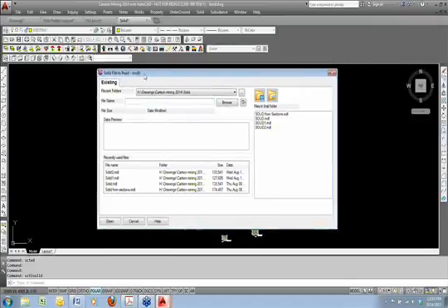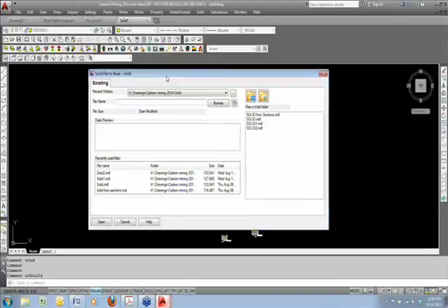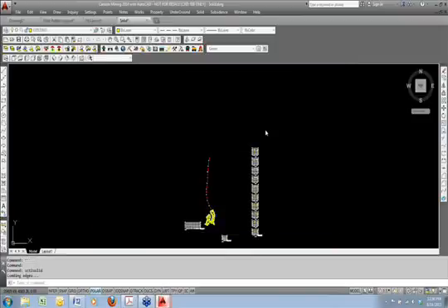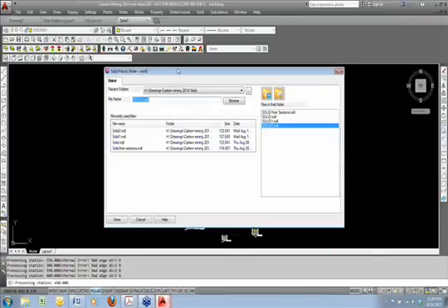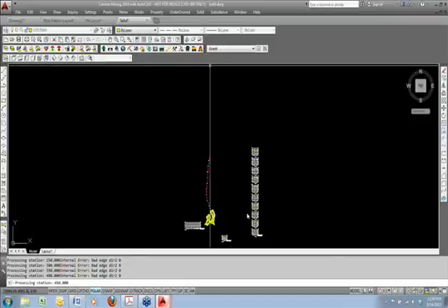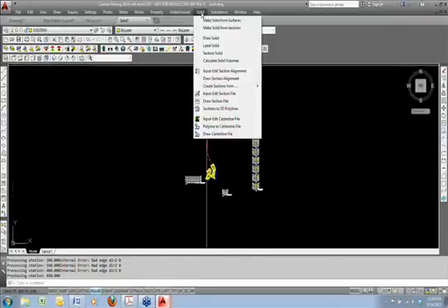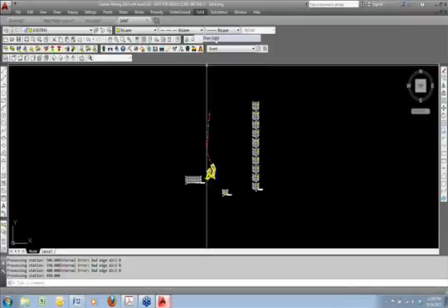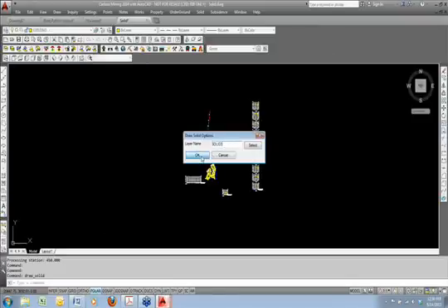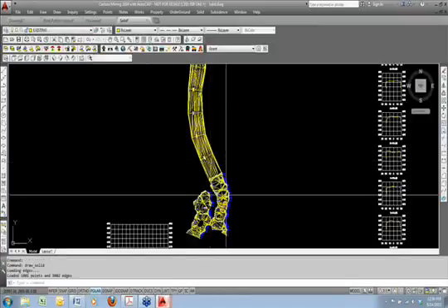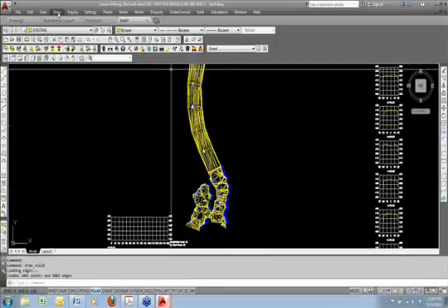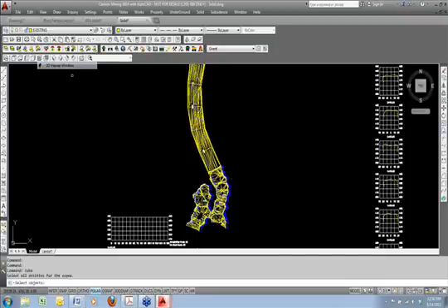And then finally, the solid file to read. This is what I'm going to merge into. And we can just merge into the solid 2, which is what we just made. And this is the solid to write. And we'll just call this one solid 3. And then we'll draw it. Draw solid, solid 3. Put the layer solid 3, and then it just tied into the existing solid and continued that down. Now we'll look at this whole thing together in 3D. Solid 2 and solid 3.